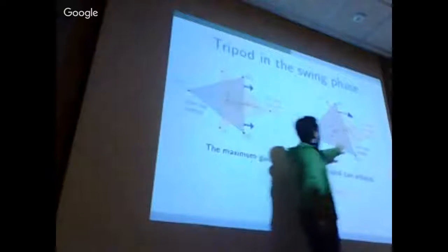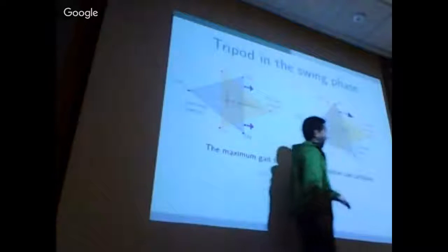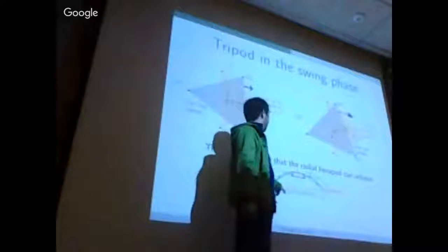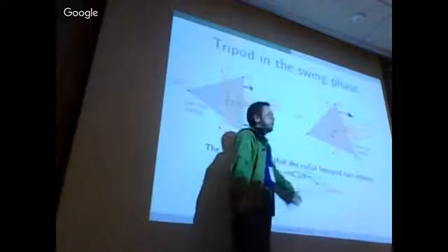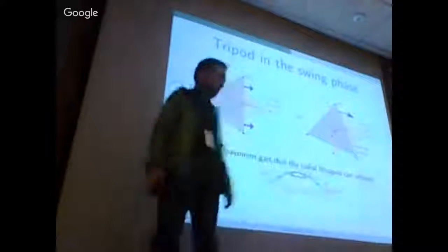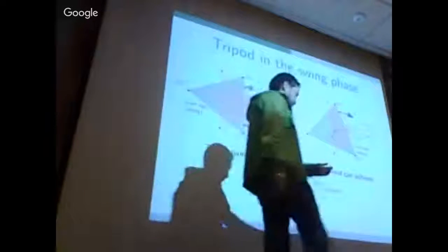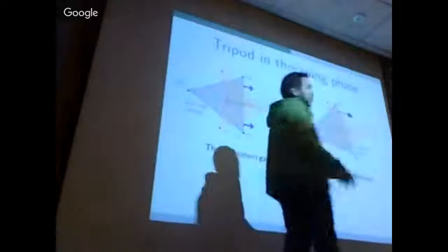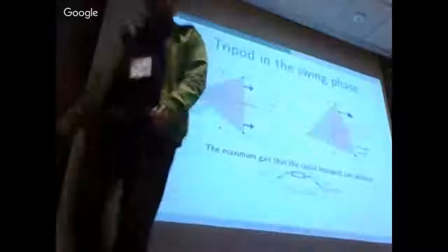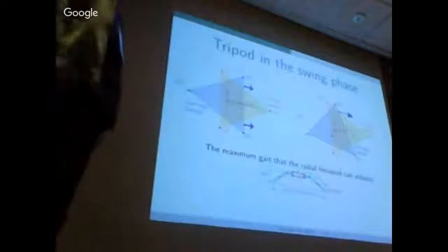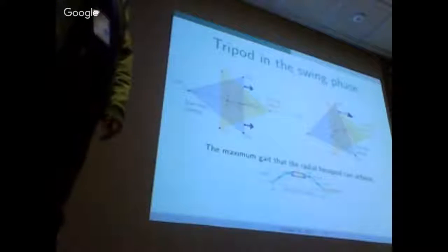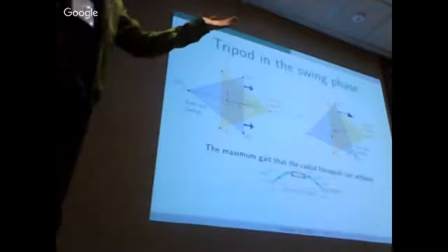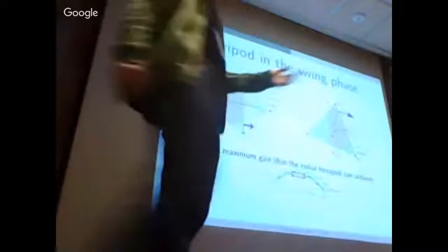This distance that I showed you, Lmax, we made it 70% of this maximum gait distance. That means that I have some working range to walk, and also to extend a little more or a little less, depending on how we perform the gait cycle. Right? So that's how we define the desired position for the tripod swinging ahead of the robot.